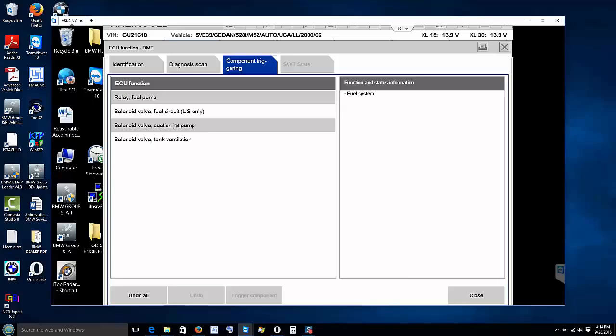Oh no, it's VIN specific, because BMW doesn't allow clusters to be switched between chassis because of the mileage data that is stored. They are different. Yeah. But yes, you can manipulate it. You can take out the EPROM chip and put in another EPROM chip.